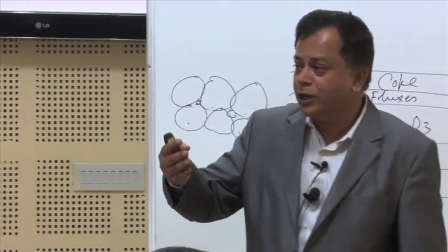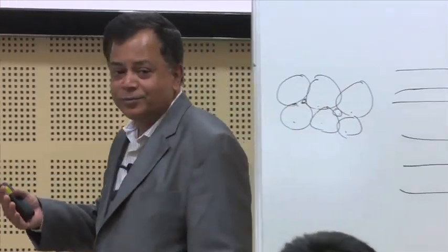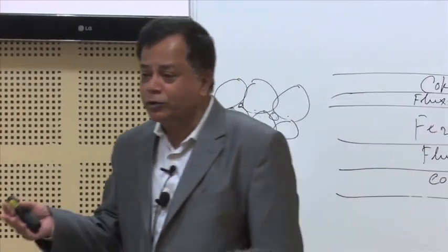So, 42% material I have unnecessarily transported for 500 kilometers, 700 kilometers, I paid money on that, and then I have also used my energy for the conversion. In a power plant, how do you convert energy? That is, you generate steam, and then with that you run your turbines, isn't it? So, that is basically a deterrent for steam generation, because you are not getting heat. So, unnecessarily you are consuming heat also.